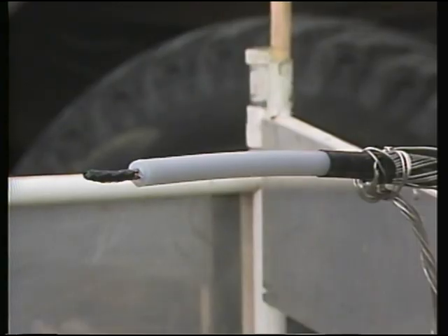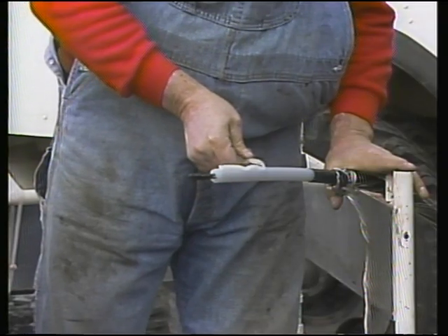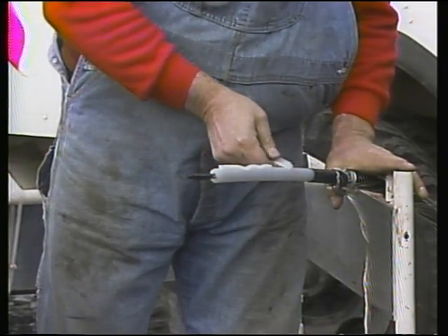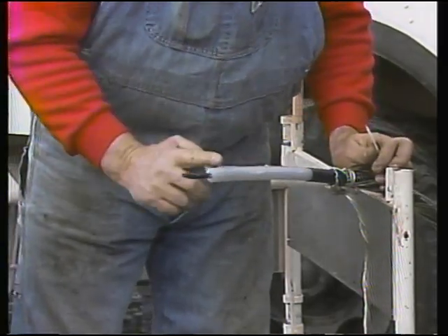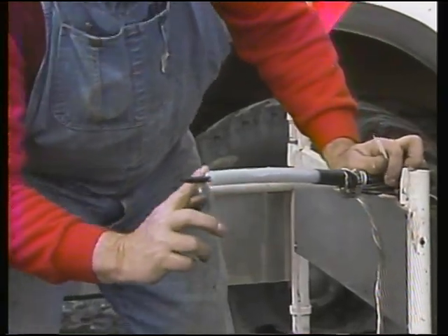This worker has already cut off the concentric wires and removed the semiconductive insulation shield, the primary insulation, and the conductor shield layers. He's also cleaned the cable insulation, tapered it, wire brushed the conductor, and covered it with tape. To make it easier to slip the stress cone onto the end of the cable, the worker applies a silicone grease to the cable insulation and then to the stress cone.